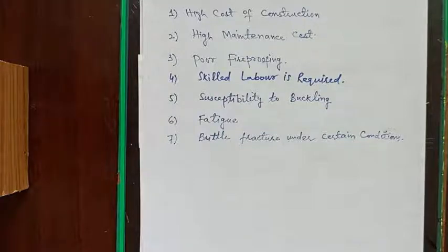Another disadvantage that is associated with steel is its susceptibility to buckling. As the length and the slenderness of a compression member is increased, its danger of buckling increases. For most structures, the use of steel columns is very economical because of their high strength to weight ratios. Occasionally, however, some additional steel is needed to stiffen them so they will not buckle. This tends to reduce their economy.